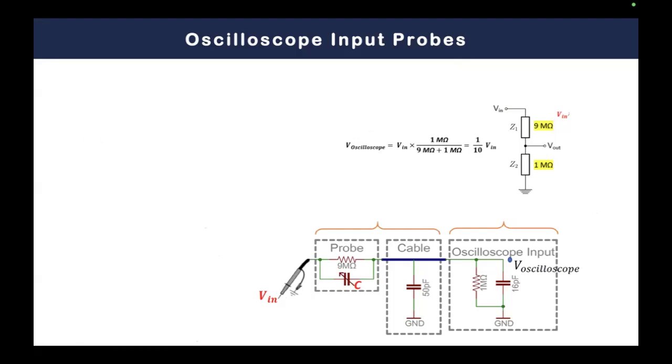Usually, the problem with attenuation is not the attenuation itself. The problem with attenuation is that you don't know the attenuation, so you don't have the capability to compensate for it. In this story, the good news is that we know that our signal will be divided by 10. There is an attenuation factor of 1/10 with respect to our signal.